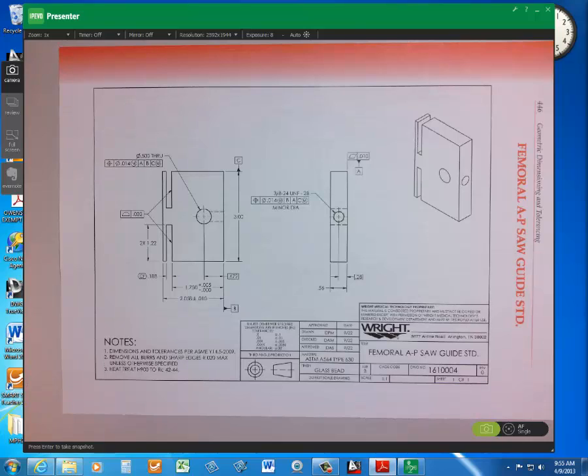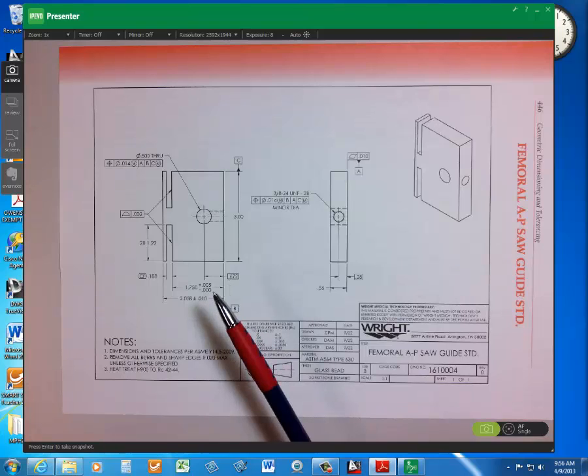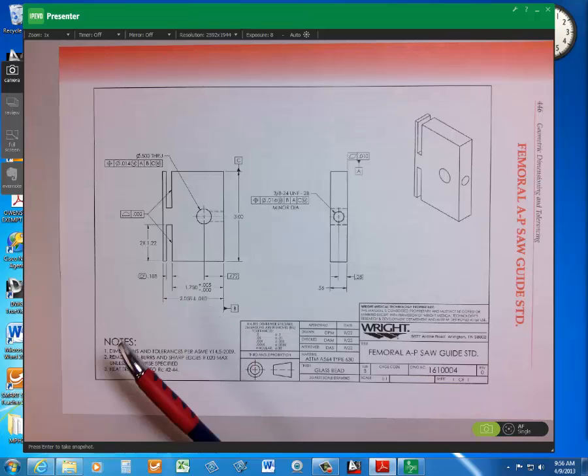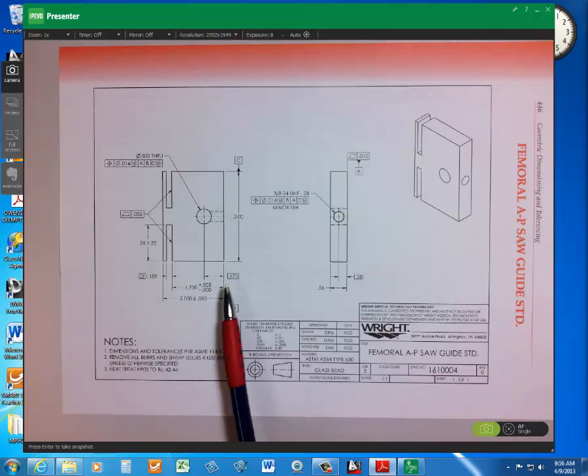Okay, so on the half-inch dimension, give the location dimension from datum B and the location application relative to datum C. So the feature is located, let's see, 0.672, am I looking at the right one? Yeah. 0.672 basic, okay, from B. All right.